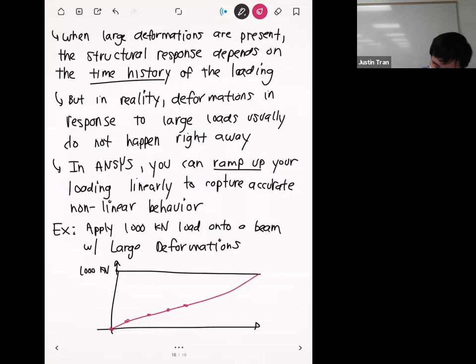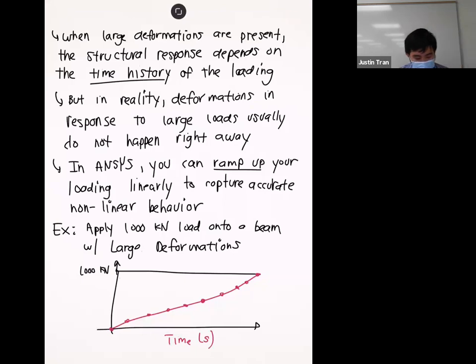Okay. And so it'll run one simulation where the load is only maybe a tenth of this. And then after that, it'll run another one automatically by increasing that by a small increment. Okay. And then eventually, you'll reach the point where you're at full load, but you approached it in several different steps instead of just going right up to the maximum load right away. Okay. And so it does this over a period of time. All right. Any questions on this? Okay. All right.